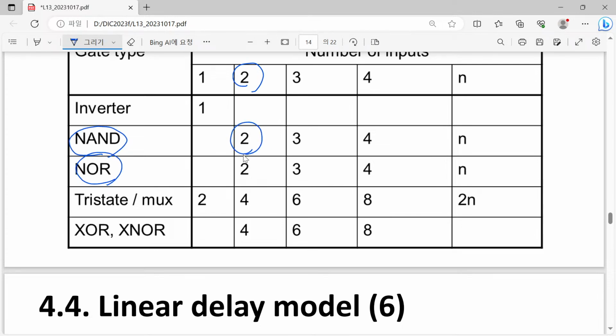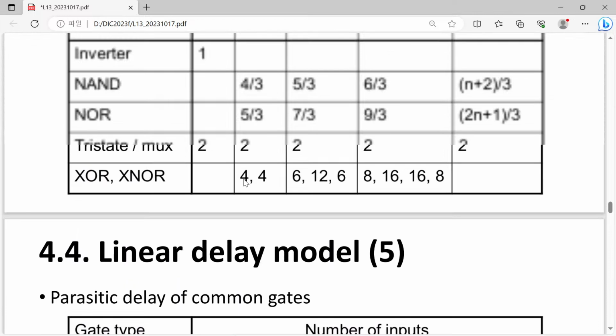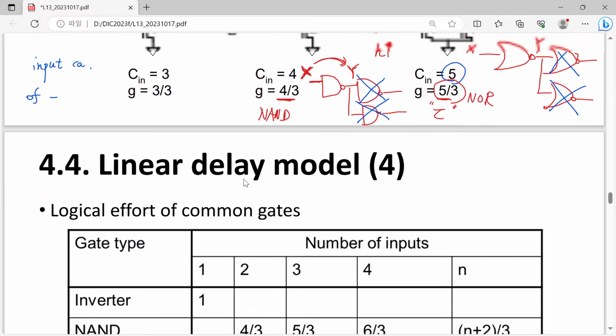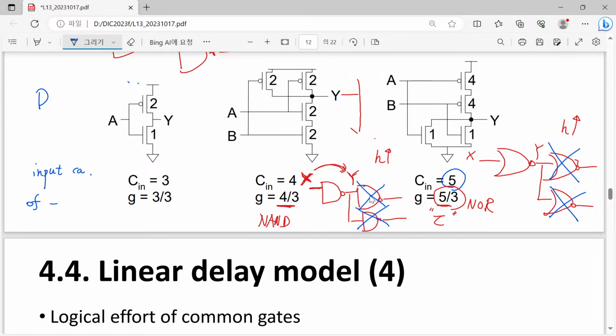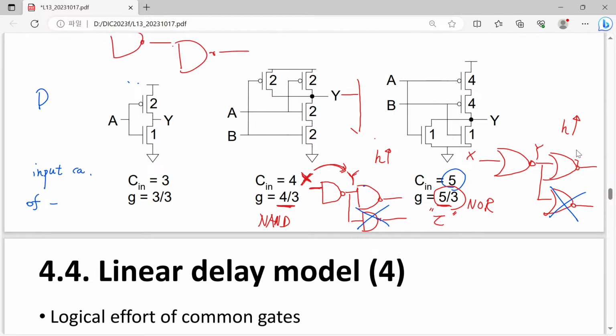Then you can see that in this case they are the same. So simply speaking, when you have just an unloaded NAND and unloaded NOR, then you can expect a similar scale of propagation delay. But when you add one single NAND and one single NOR load, then you can expect that, wow, now you have longer propagation delay for the two circuits.